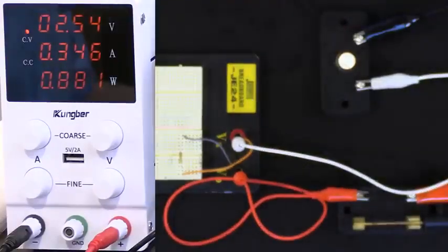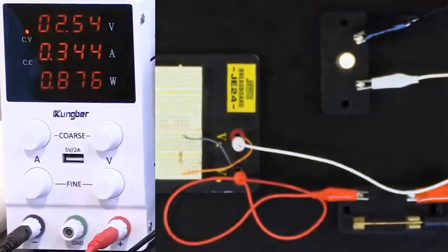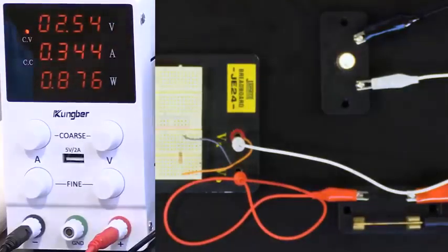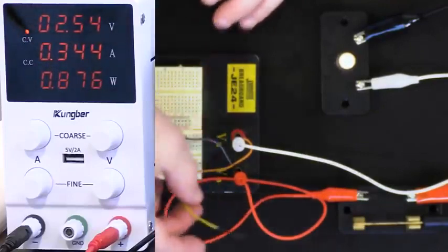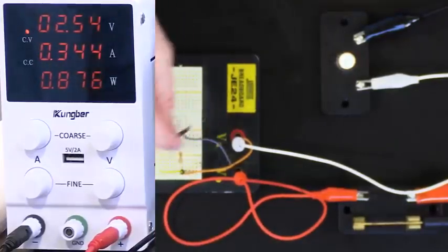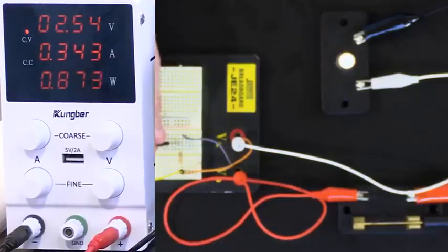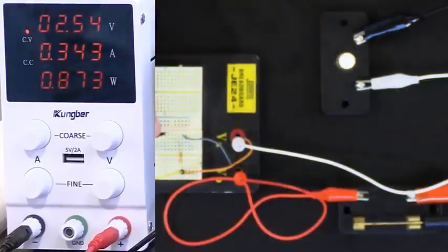We can see the light bulb here, but in this case, what I've done is now the circuit is going through this resistance as we have done before. We're still lighting it up. All right, what is going to happen if I have a stray piece of wire, say some aluminum foil blows into your circuit, or something happens where parts of your circuit are connected across each other? So for instance, you might have this wire here that came loose somehow, and it's just banging. Maybe you're in a rocket, and eventually it touches the other side of this resistor. What's going to happen? Then the electricity is going to want to flow through the wire instead of the resistance, because electricity always wants to go through the path of least resistance.